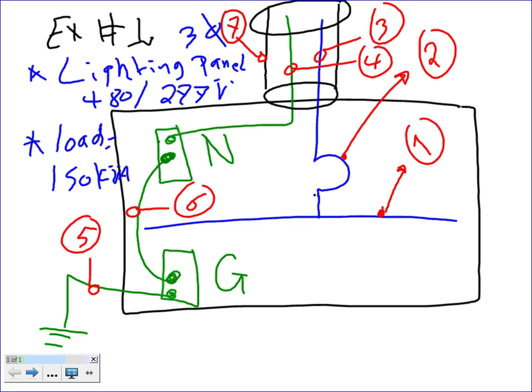Now, disclaimer. The continuous load has already been incorporated in the 150. Some of you will ask me, what happened to the continuous load? I already added all my volt amps, multiplied it by 1.25, and I came up with a big chunk of 150 kVA. My load. I need to size a panel. It's already added, and I gave you the lump sum.